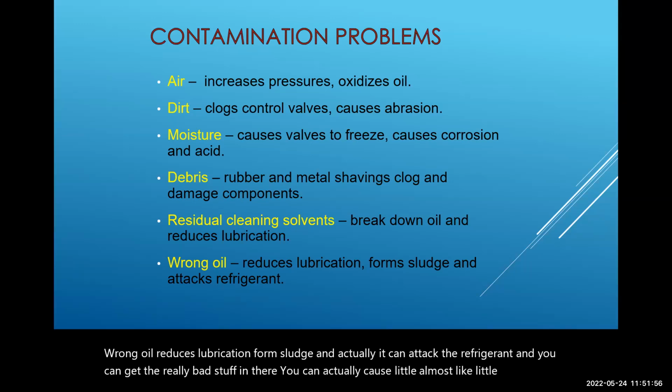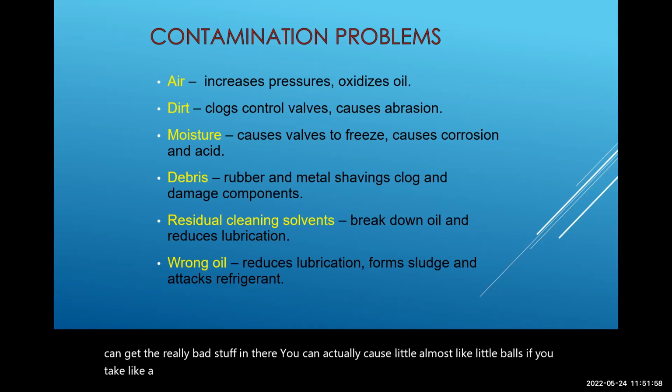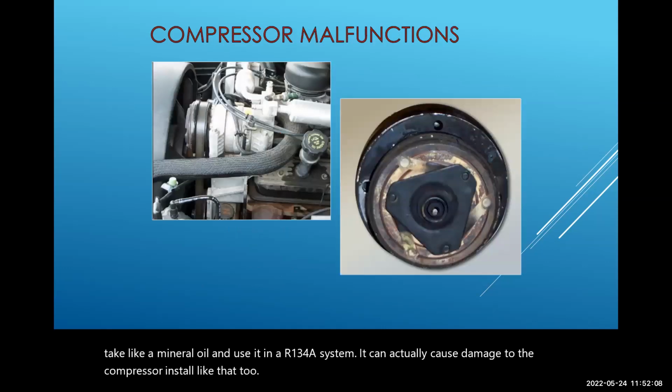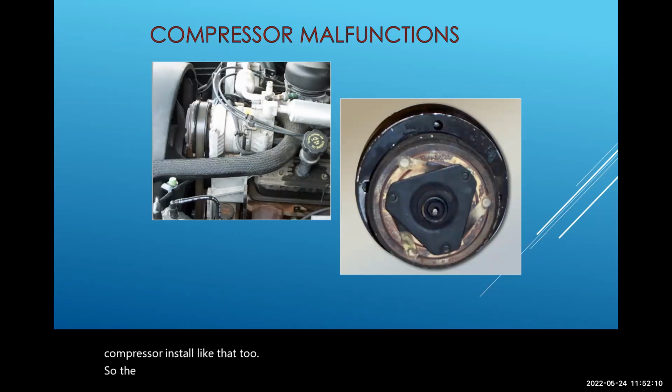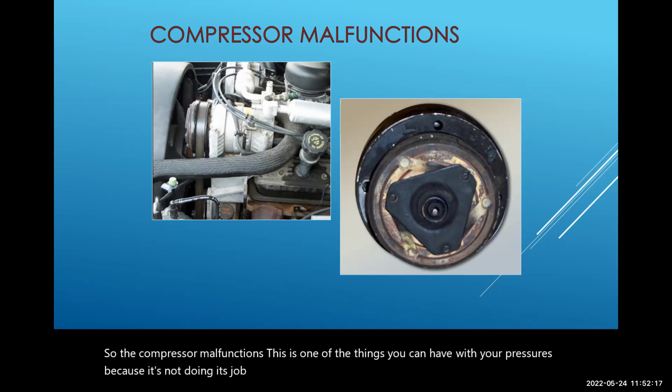If you take a mineral oil and use it in an R134A system, it can actually cause damage to the compressor and stuff like that too. So if the compressor malfunctions, this is one of the things that can happen with your pressures, because if it's not doing its job properly, we can have issues with pressures. So let's look at how the AC system components can fail.